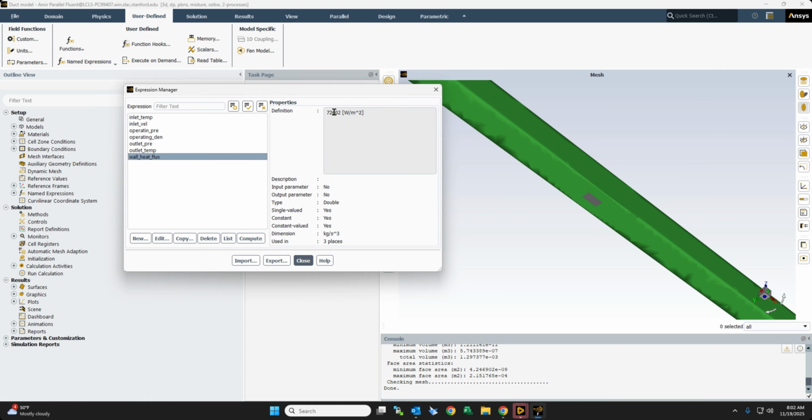the flux, the heat flux going to the heating element, right? So, and we are gonna change this value when you have an expression defined here. Changing is very easy. You just need to come in here and like you can manage all your boundary conditions basically here in this window, right? And also you can use it for parametric studies later.